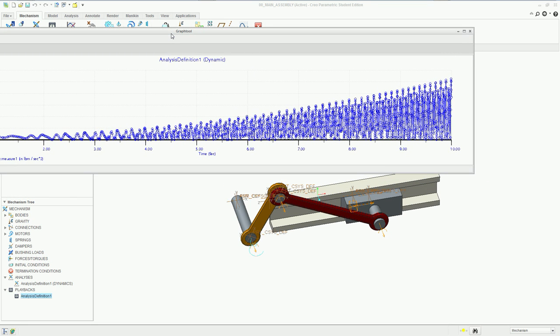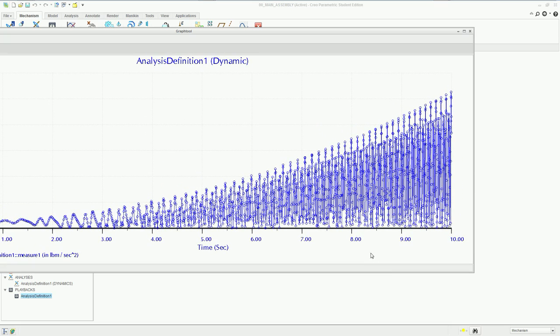Because the acceleration is applied, the connection force, or the reaction force, is going to increase because we have our speed increasing constantly. It's not a static value. If you remember the velocity graph, it constantly goes up. So the speed of the link rotating around that shaft is going up tremendously. And this is exactly what we would expect of something that acts like that. The connection reaction would eventually go up.